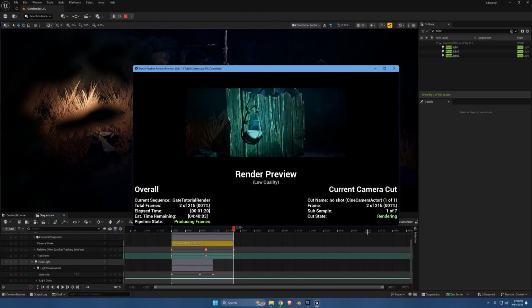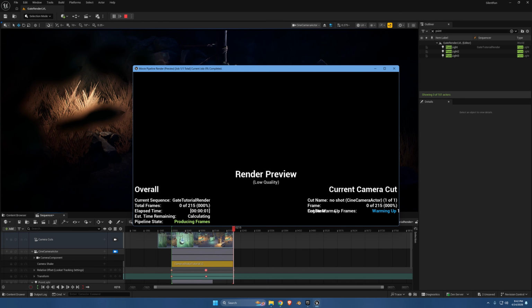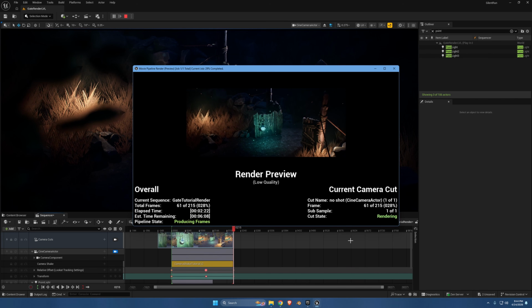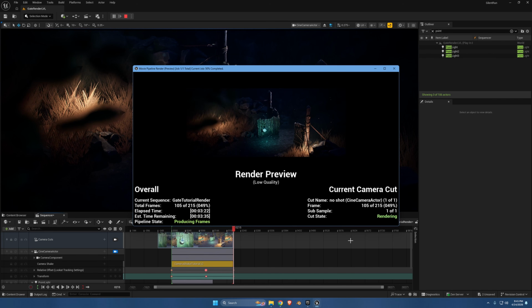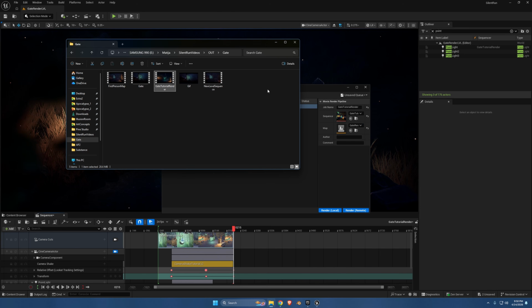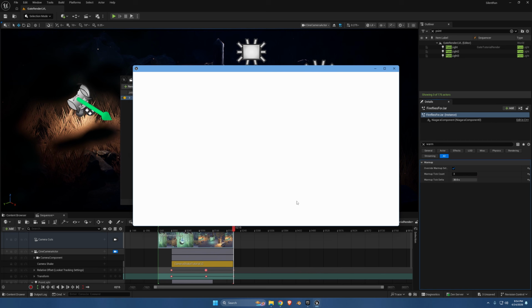and see what happens. If it takes too much time, you can reduce the settings a little bit, but it shouldn't, because we are using real-time lighting here. We are going to have some warm-up renders here, warm-up frames I mean, and it should render everything quite nicely for us. So I noticed here that once the rendering was finished, I also had the option of JPEGs activated, so you can just unselect that so it doesn't render every single frame out individually and place them in your folder. We just want the MP4 at the end of this.